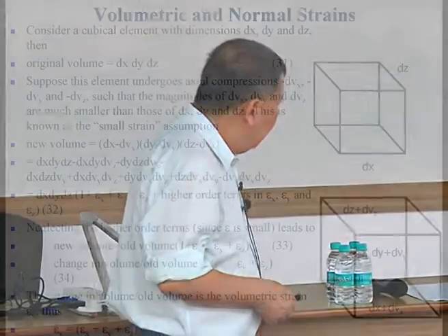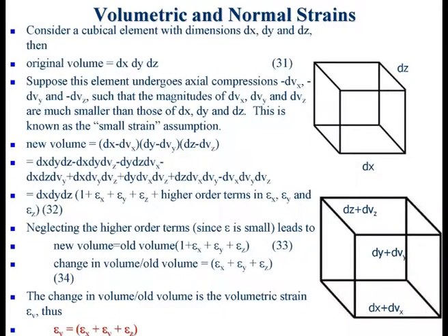But the soil will control the pore pressure inside. So you cannot control the pore pressure. Even the boundary pore pressure is not controlled. So in the undrained analysis, you typically do not need to set a pore pressure boundary condition. So these are the 2 ends of the string that we were talking about yesterday. And then we went on to define the volumetric strain.